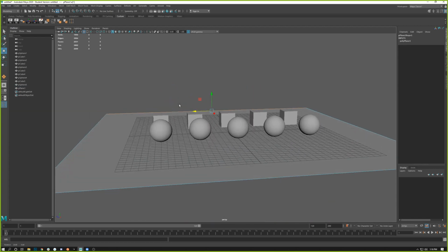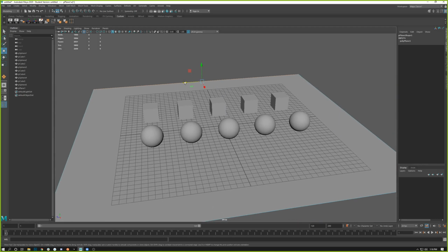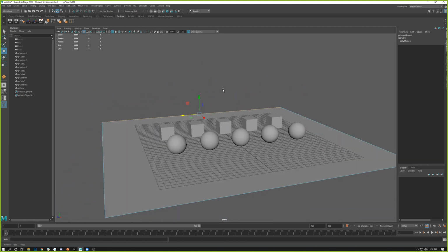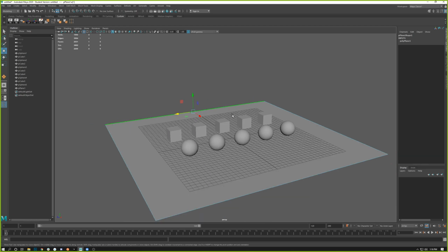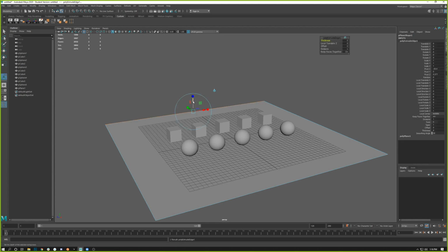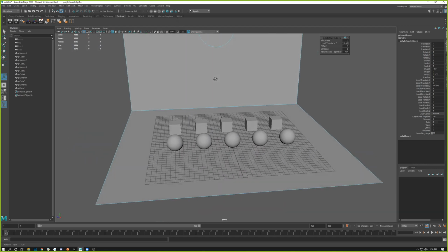And we've talked about in the tool series, just various tools, and one of them was Extrude. And I'm just going to use the Extrude tool to bring this edge up. So to bring up an edge in edge mode with Extrude, just select the edge that you want and hit Control E. Normally we do this with face, but I'm showing you how to do this with edges. And that's all I'm doing, just bringing up that edge. So I'm making a back wall like that.